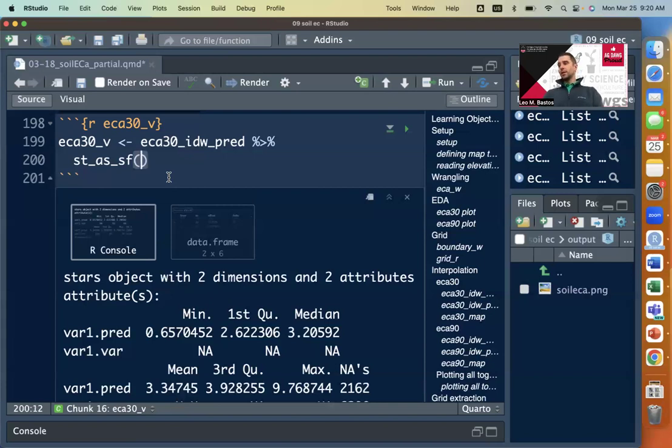So we're just bringing here, we have to change a couple of arguments here. The first one is called s_points. We want to say false. The default here is true. And if you don't change this behavior, it's going to give you the centroid of each raster cell as a point, and that's the data it's going to give back to you. By setting it to false, like we're doing here, it is actually going to transform each one of the raster cells into a small polygon. It's going to give us polygons back rather than points.